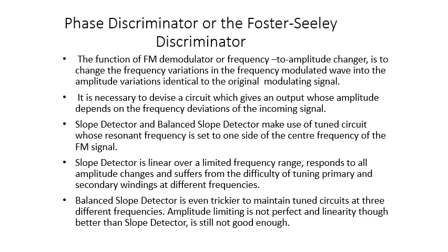The earlier methods or the basic methods for FM demodulation are slope detector and balanced slope detector. The basic concept of functioning of a phase discriminator is the same as that of slope detector and balanced slope detector. And this concept is that at the output of the circuit, we intend to get the S-shaped frequency response.